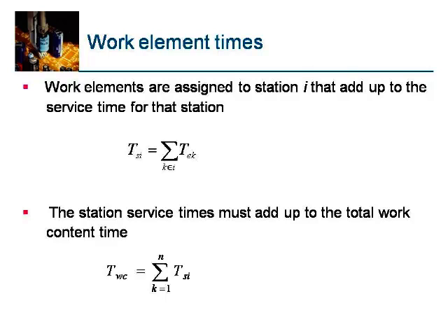The total work content must be given to various stations. The assembly of all operations cannot be performed at only one station, so it is divided among several stations, and at each station certain work elements are performed. While assigning these work elements to each workstation, you need to follow the precedence constraints. At the same time, the total work content at each workstation should be more or less equal.